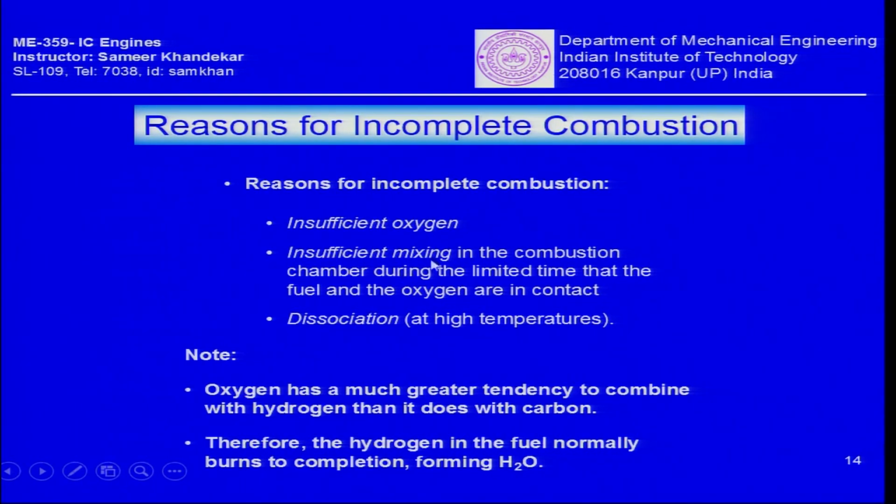That means the fuel did not have oxygen molecules around it, and in the combustion chamber there was probably limited time because the engine is running fast. The fuel could not completely burn inside the combustion chamber, and therefore, with limited time, the exhaust valve opened and the unburnt carbon actually came out as soot. Okay. So that is another issue.